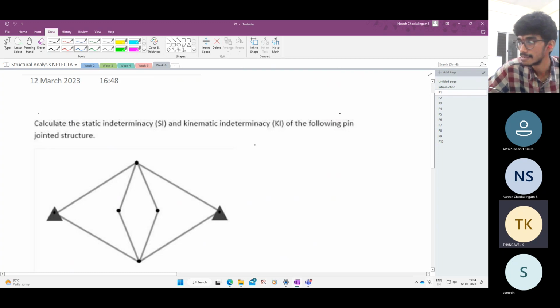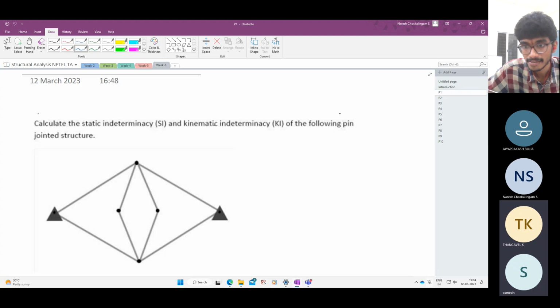Yes, Sumit. I remember one formula from my engineering days for that frame structure. It was something like m minus 3j plus 3 minus the number of internal reactions generated due to internal support or something. Am I correct? Please correct me.